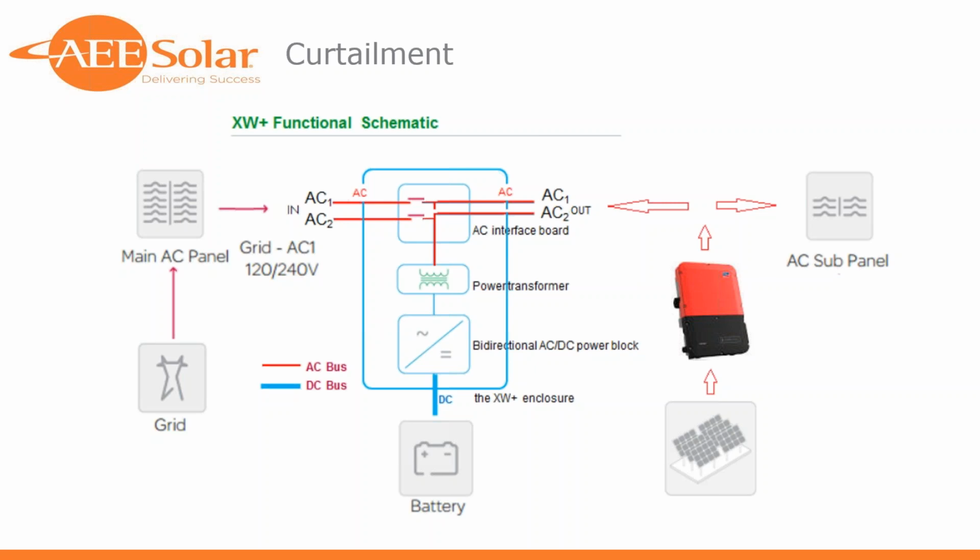It's going to look to the voltage on the DC bus to make decisions about how much power to harvest, knowing, because you've programmed it as such, what type of battery you have and how many charge amps it can supply, and having a 3-stage charge profile for that battery type to know that A, I'm in bulk, B, I'm in absorb, C, I'm in float, and knowing how to tailor the wattage it's harvesting from the array to supply the right amount of power to that battery.